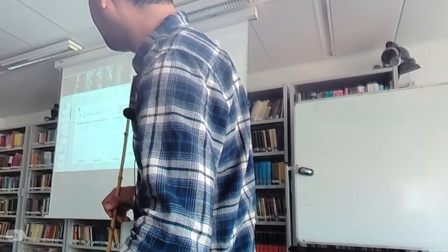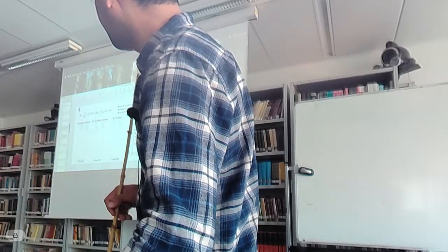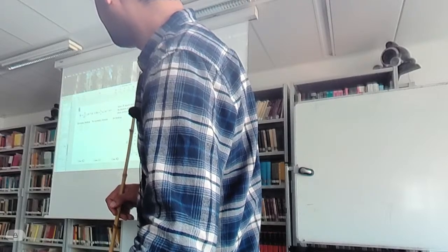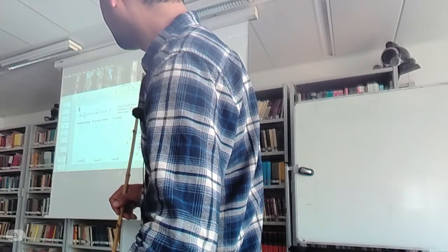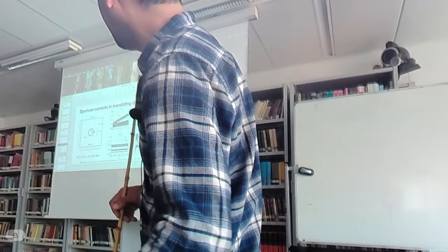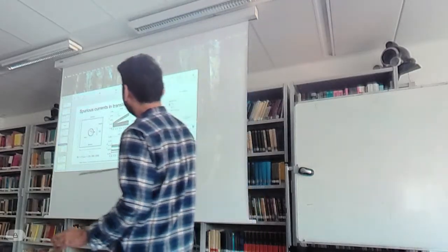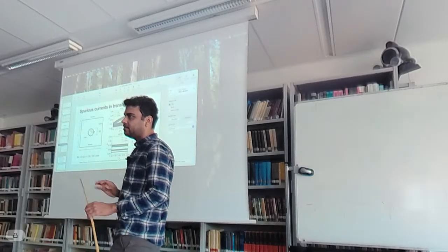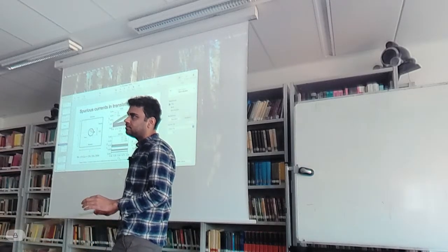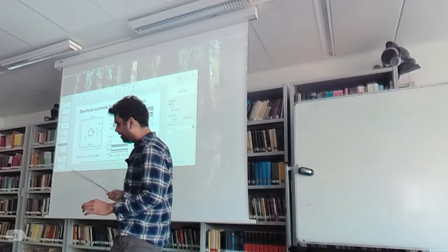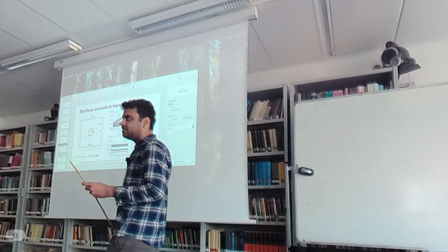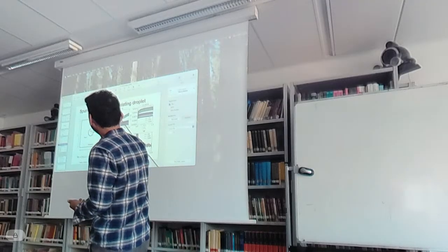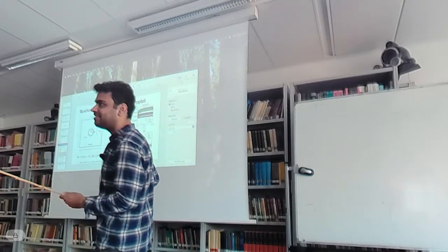We did spurious currents for translating drops. For static drops, for CSF or for our method, which is CSS, the spurious currents die to the machine accuracy, because it's well balanced.